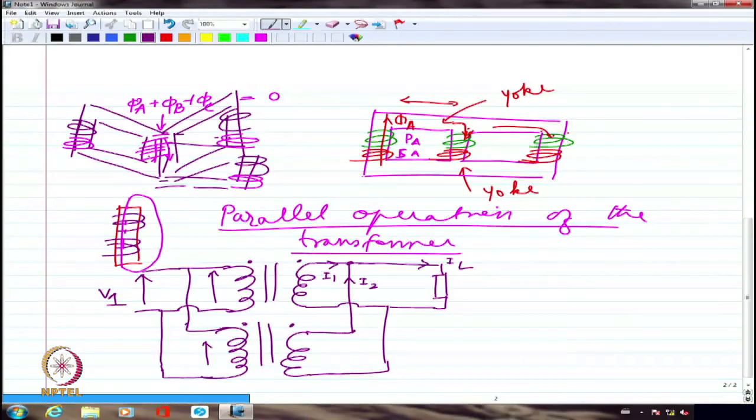One way of doing it is to remove that 100 kVA transformer completely and put in a 1 MVA transformer. Even then, there is no guarantee that 1 MVA is going to be sufficient tomorrow. So rather than that, along with this 100 kVA transformer, another 200 kVA transformer was added, one more 200 kVA.